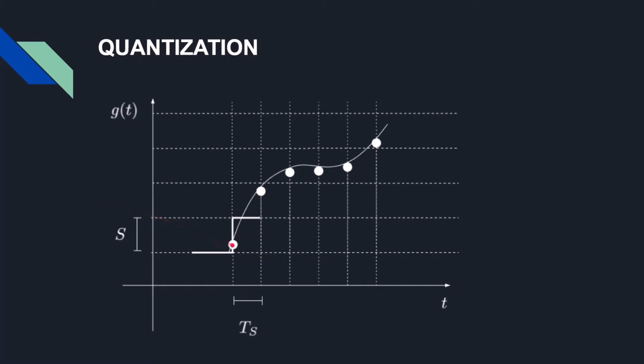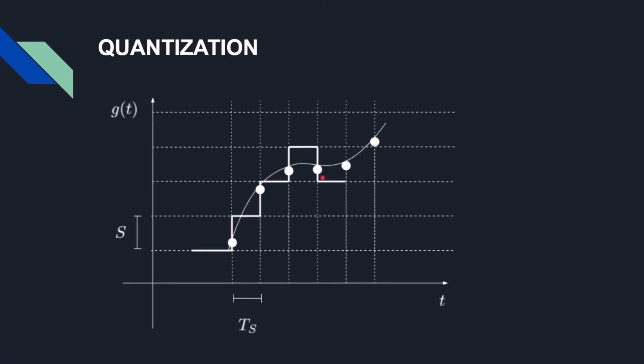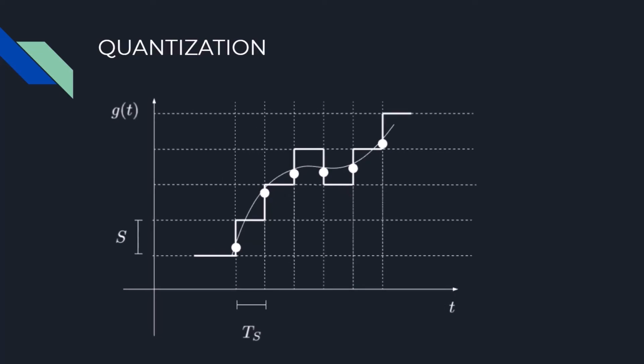As we can see, g(t)'s value at the first sample time was greater than the first level, so we jumped one step size above and, maintaining the same level's value, we horizontally move towards the next sample value of time and do the same. Now, g(t)'s value is less than the current level at the current time value, so we jump down and hold the new value to the next time sample. Performing the same steps for all the samples of the original analog signal will generate the quantized signal.